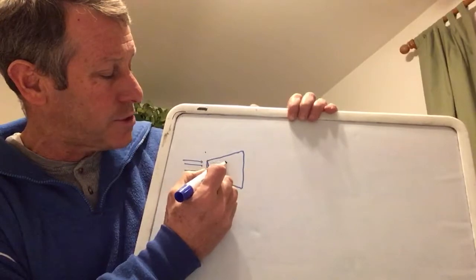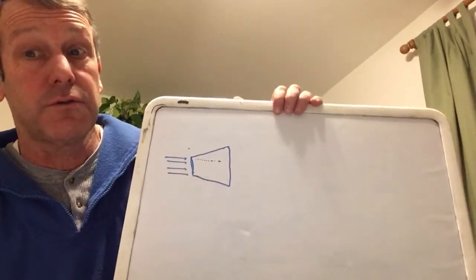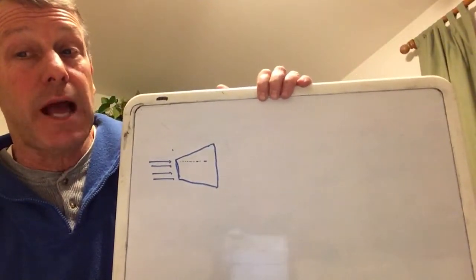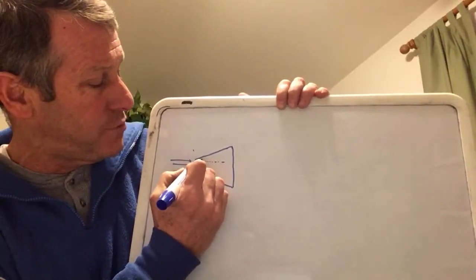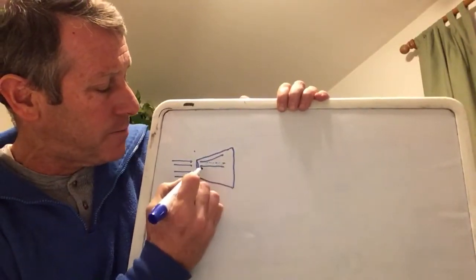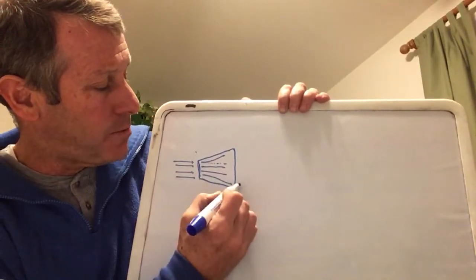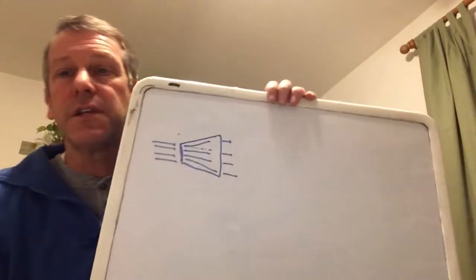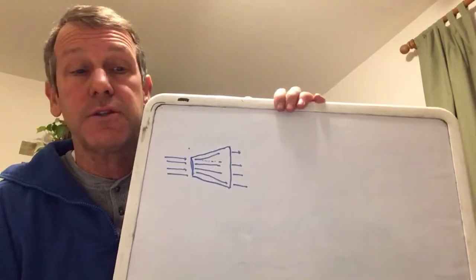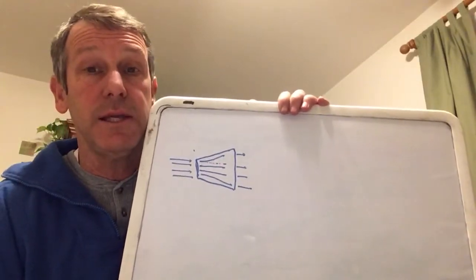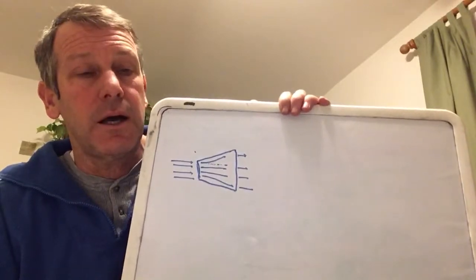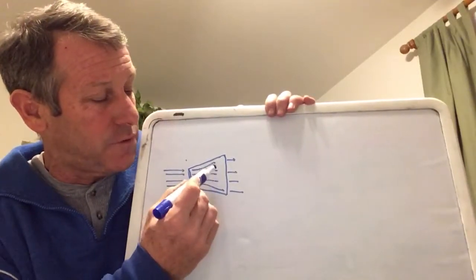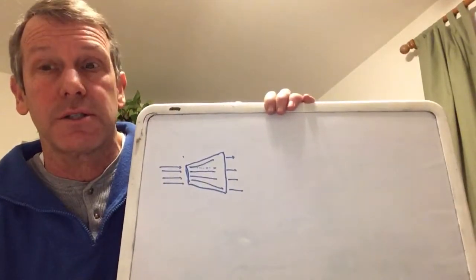You would think that a fluid might go in a straight line because a fluid's a particle, and particles follow Newton's first law. They like to flow in a straight line. But at the same time, gases tend to spread out and fill available space. So these fluid lines will actually end up expanding outward as it goes through the device, and will end up coming out here like this. So just check your thoughts for just a second. If I had a fluid going through a diffuser, would it speed up, slow down, or could it possibly stay the same speed? And it's the opposite of the nozzle. There is more space for it to emerge, and the gas or the fluid ends up spreading out, so it ends up slowing down as it goes through there.